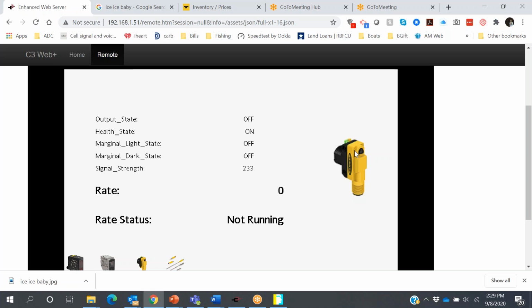You can use that by itself to let you know if you have a potential issue happening. In this example, if you have an application where every now and then your line goes down because a reflector gets covered with flour, dust, or something like that, and you have to go clean it off, well, you can start monitoring that signal strength and set basically a little alarm in your PLC that if it changes a certain amount, next downtime, and I'm actually turning the sensor slightly, next downtime, you can go clean off that reflector.